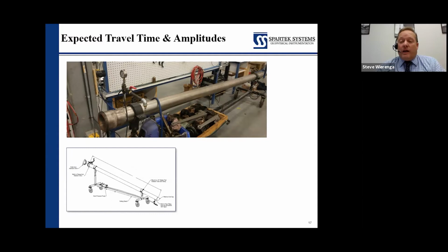It is a 5.5 or 139.7 millimeter, 25.3 kg per meter pipe. That equates to 17 pound. We're going to fill this casing. First, we're going to put the tool in it. Then we're going to fill it up with fresh water, bring the pressure of that tank up to 500 PSI, just to make sure we have good acoustic bond between the tool and the pipe.